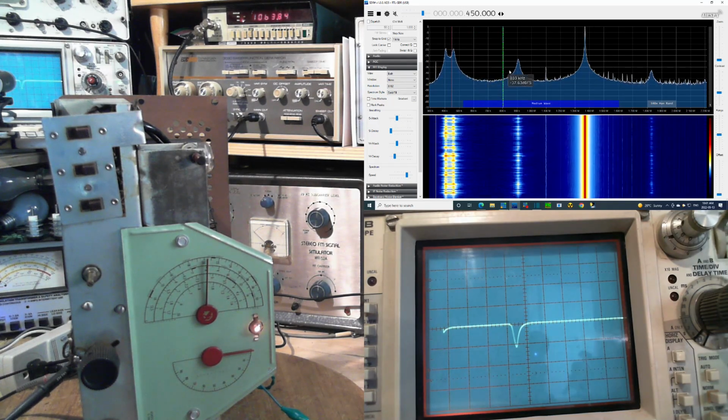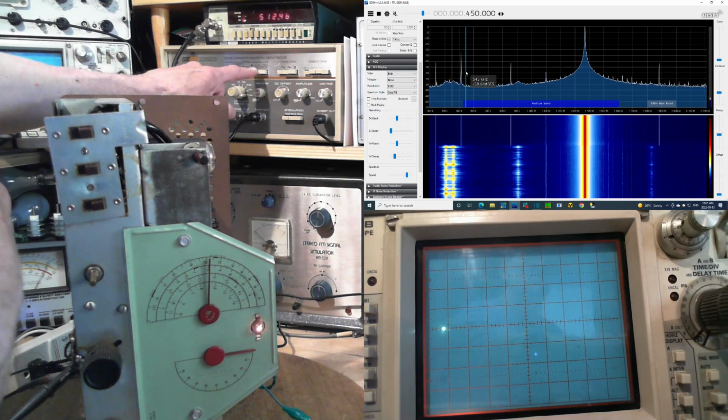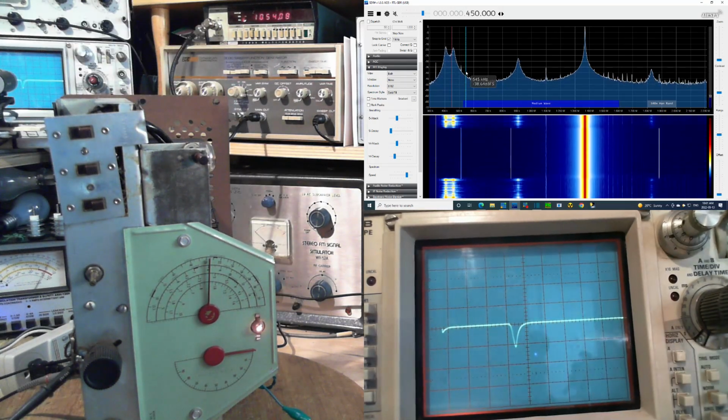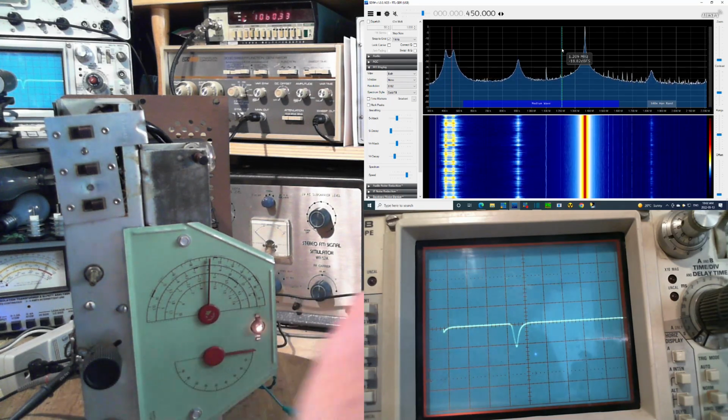This could have something to do with the sweep range I have set up. Well, actually, no. The sweep starts in this area here. Actually, let me check. 512 is the frequency it starts at. So 512 is down in this range. The sweep itself is not even passing through here. This signal has to be produced by the radio through the local oscillator effect. Okay, let me knock the local oscillator out.